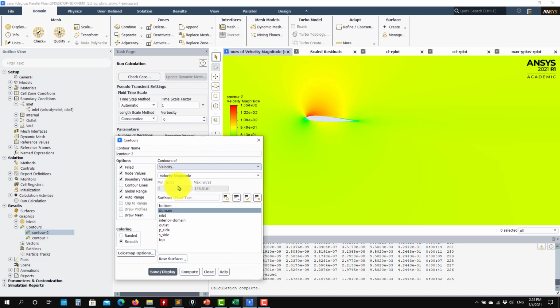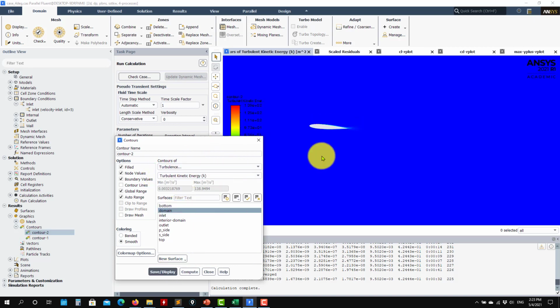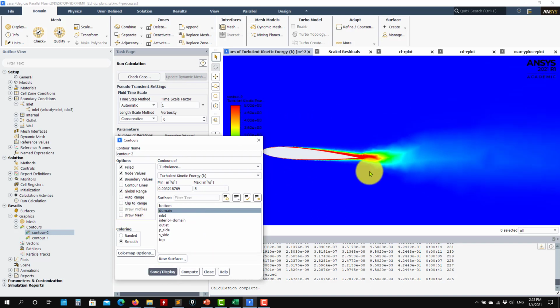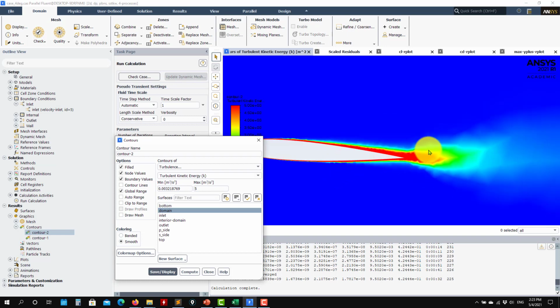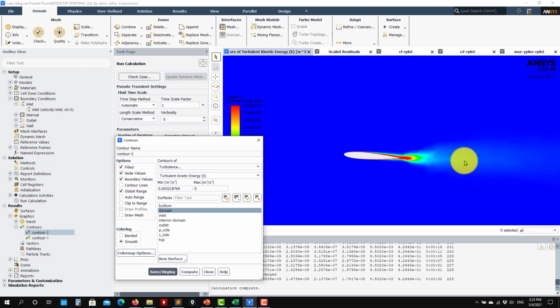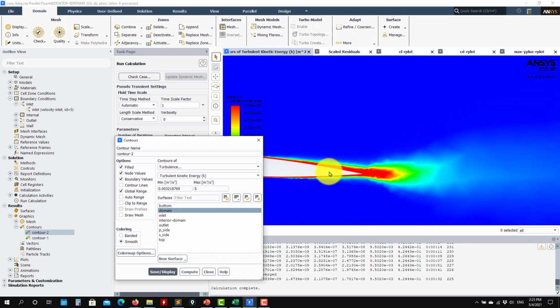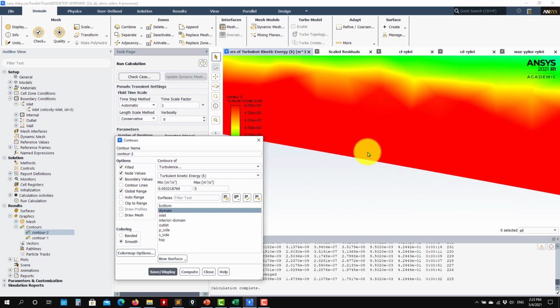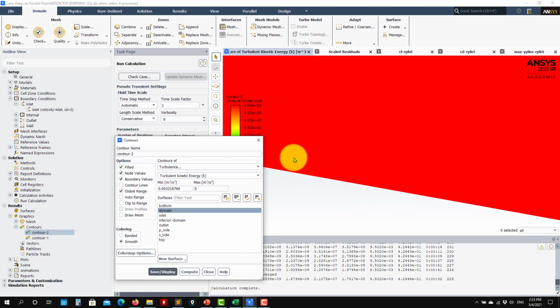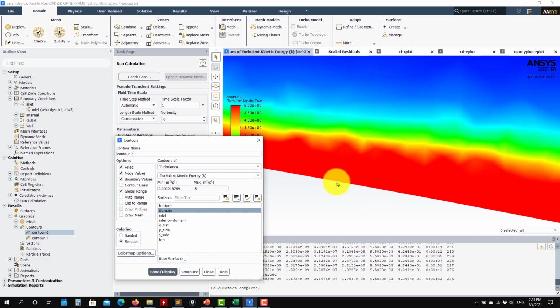So for instance, you can plot turbulence quantities. Okay, so through kinetic energy, you can change here the range. So let's put 5 there. Let's see here that click to range. Okay, so where you have large values, in red, let's say, is where the kinetic energy turbulence model is kicking in. And see that close to the walls it is a non-zero value because we're using the wall function now, Y plus more than 60. So it's a non-zero quantity.